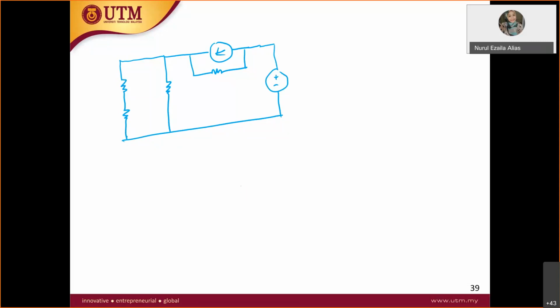Okay, so you have V-test over here, and then you have I-test over here. And then I said this is gm V pi, so this is R naught. So the current flowing here is equal to the I-test minus gm V pi. Okay, so you have RE over here, so the current here is approximately equal to I test. And then I find the current here. This is R pi, this is RB, and minus plus V pi.